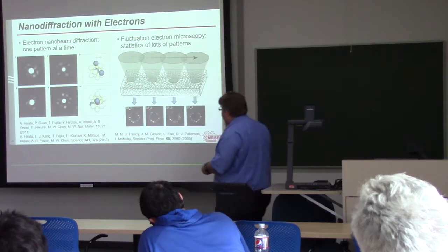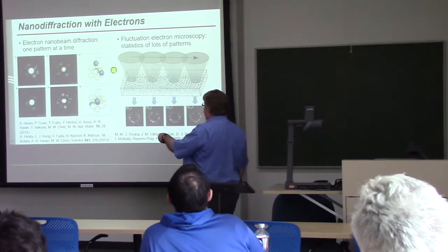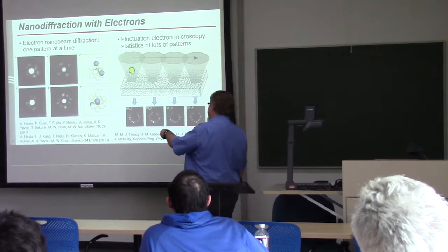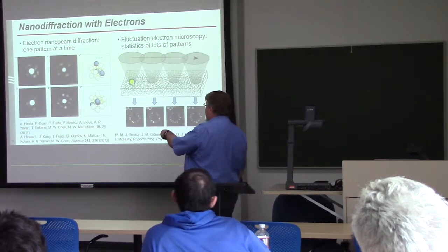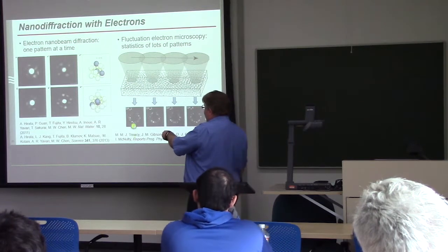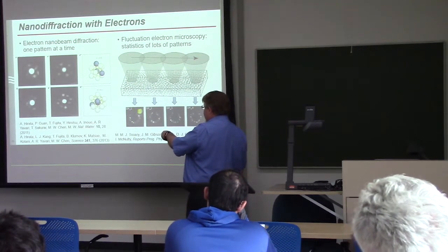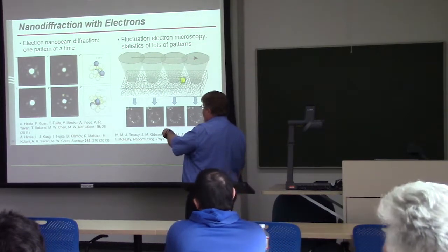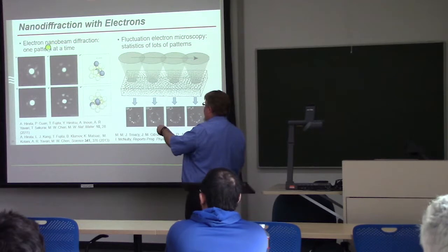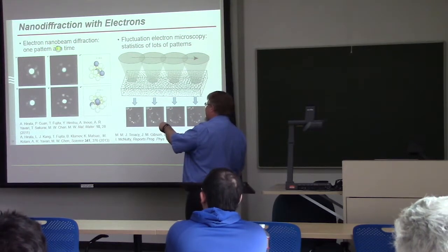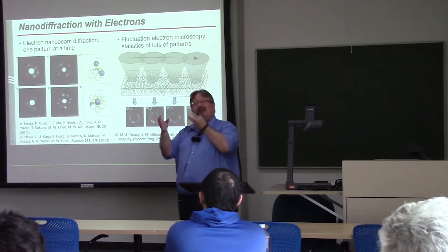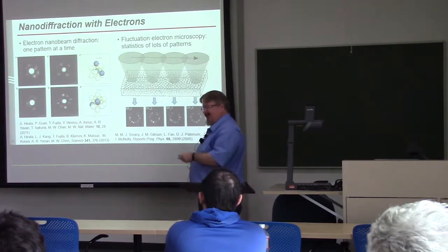So this is a pretty good description of the short-range order, nearest neighbor and next nearest neighbor, for metallic glasses. We can get a little bit of additional information by doing diffraction at very short length scales using focused probes of electrons. It's possible to make electron beams that are a nanometer or less in diameter and measure Bragg diffraction using them. There are 2 techniques based on this fundamental technology. One of them is called Angstrom beam diffraction, despite the fact that the beam is about half a nanometer. So it's a couple of angstroms rather than 1, but it sounds good.